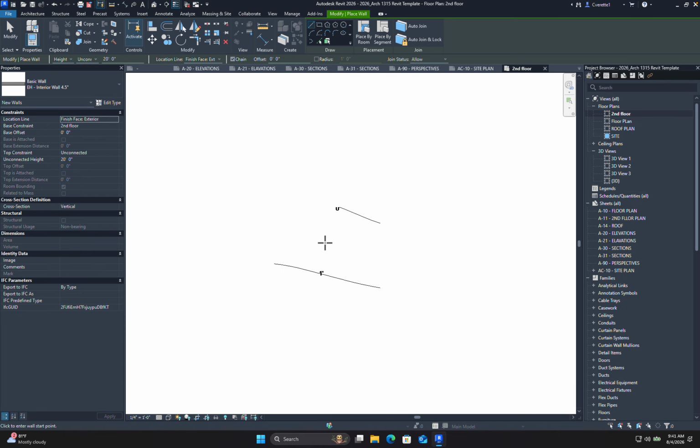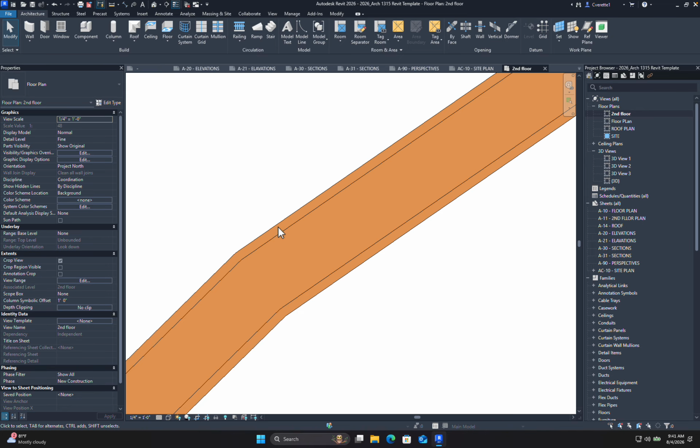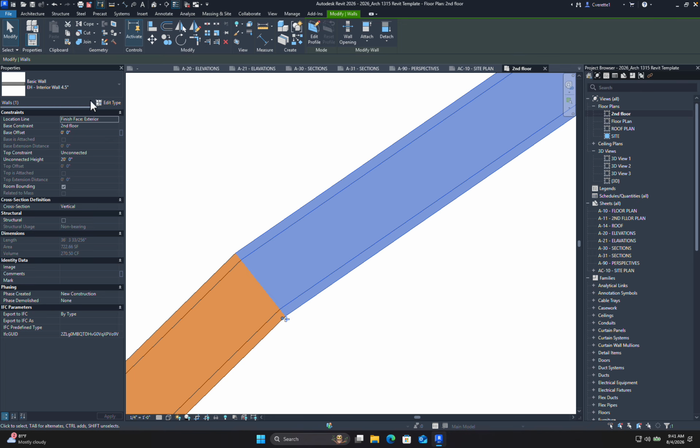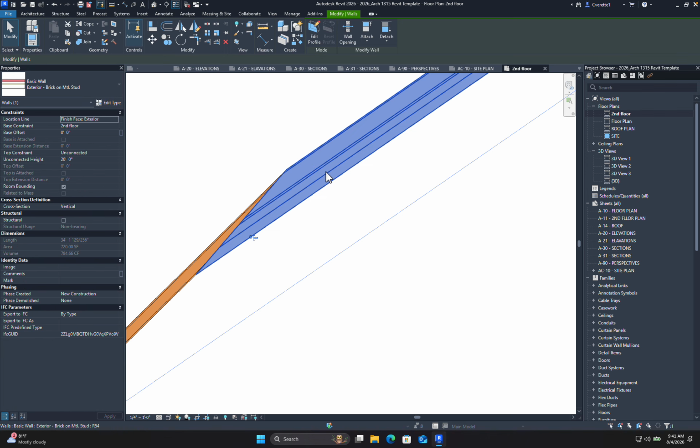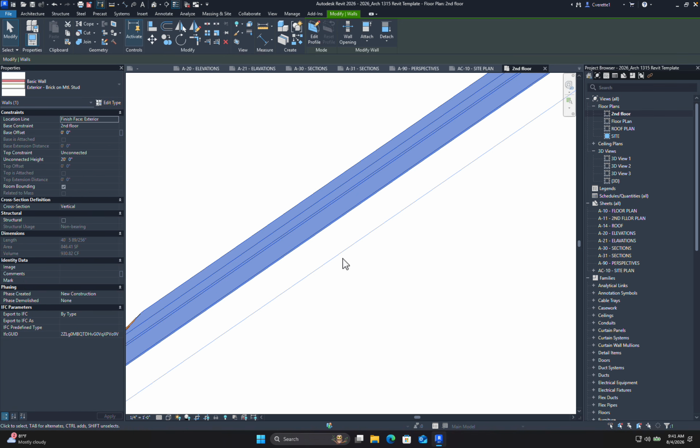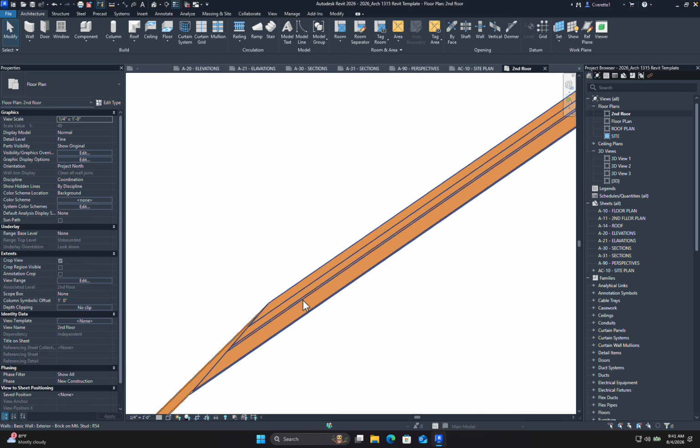Don't get me wrong, there is something kind of nice to be able to just go like this, and suddenly you have architecture, right? It is pretty cool, the fact that I now have the inside, the outside relationship. I can click on a wall, switch this to say something else and immediately have a different wall, right? I can hit spacebar and flip that wall. So, I mean, there is really nice.